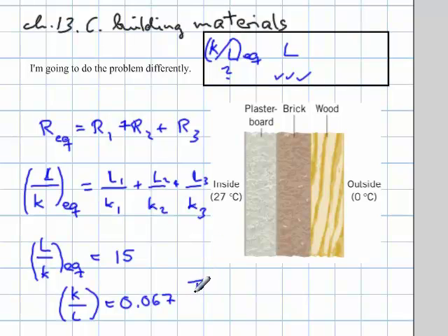And then the units on this one here is joules divided by second, meters, Celsius degrees, and again some kind of unit here for the L in meters or centimeters or what have you. I have to write that on here too. So this first part here can be readily compared, and as I said, the conductivity went down, which makes sense because we're sandwiching these together in series. The heat resistance should move up.